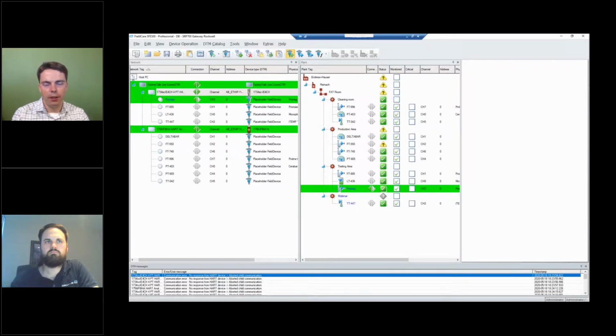In case your PLC is not HART capable, so does not have HART input cards, we can put a device in front of it to get this. But the precondition is that the device is speaking HART. That's a precondition, or have any other digital communication technology. So we also have some devices where it could connect, for instance, with Ethernet or Wi-Fi. But you have to have some technology available to get it out of the instrument, because otherwise you just get a current and then you just get technically good or not good.